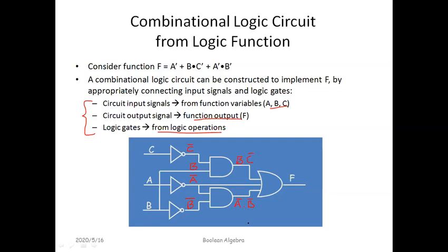These are the combination of the outputs for the two AND gates. Then, since we've got the combinations for these two AND gates, it means we've automatically got two of the three inputs to the OR gate. So the third input is coming from the middle NOT gate, which is A bar.